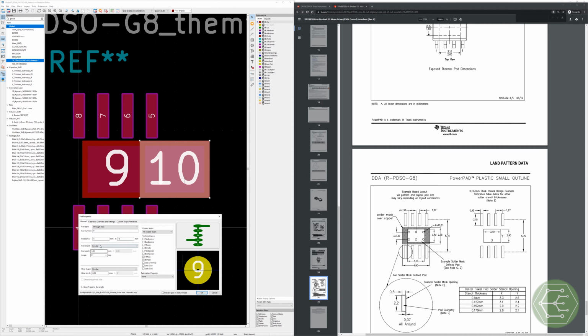And we want the pad size to be, well, let's just make it something reasonable, like 1 millimeter. What's the closest we are to the edge? 1.3. So we're 0.82 millimeters from the center. So I will do 0.6, which should give us enough room to not extend outside of the other pad.